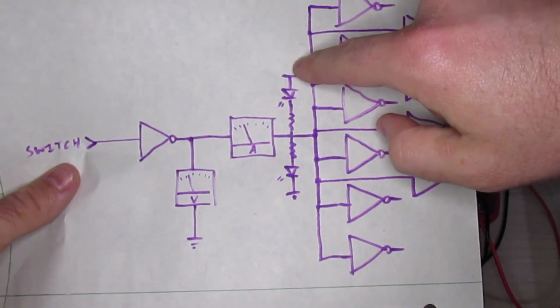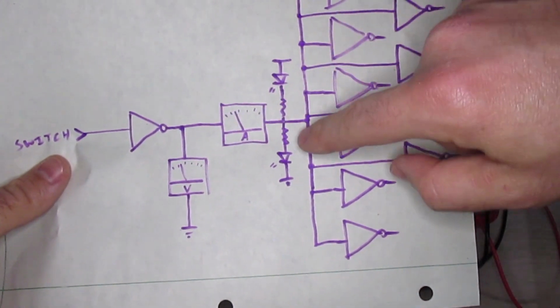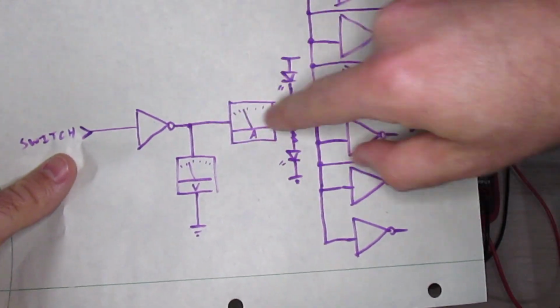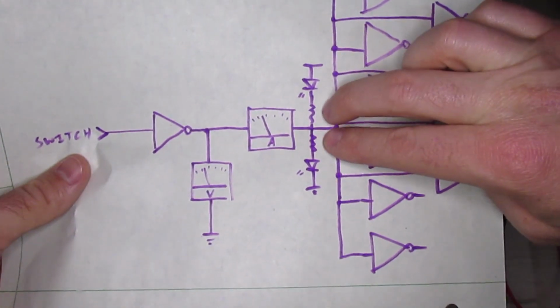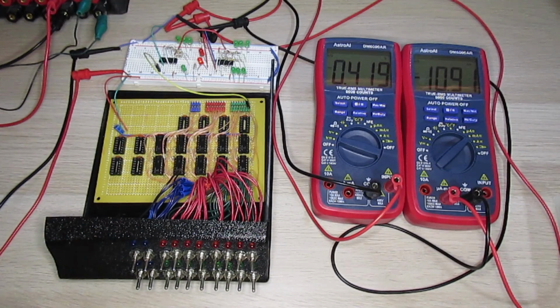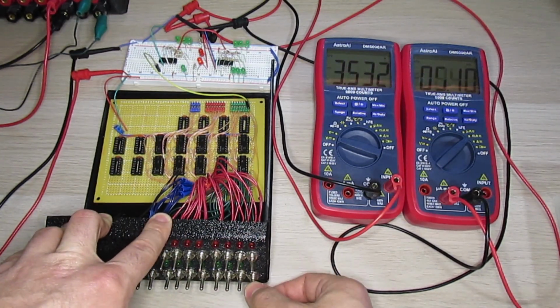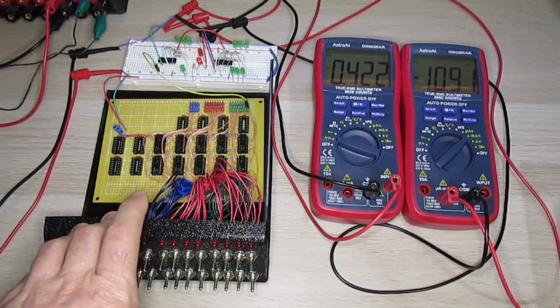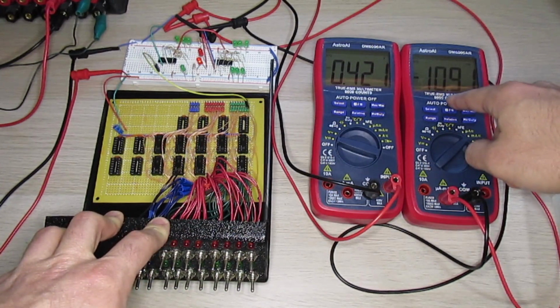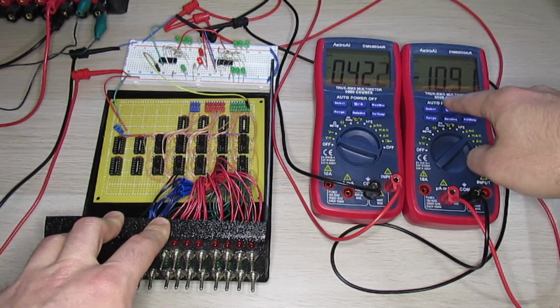And now we'll add a couple of LEDs here. One of them will be forward biased and turned on when the output is low, and the other one will be forward biased and turned on when the output is high. And right now I have some pretty large resistors here, 4.7 kilo ohms. So with those LEDs, everything still seems to be working, but let's take a look at those voltages and currents. So here in the output low state, we're still around 11 or so milliamps, so not that much more current is being drawn in the output low state.